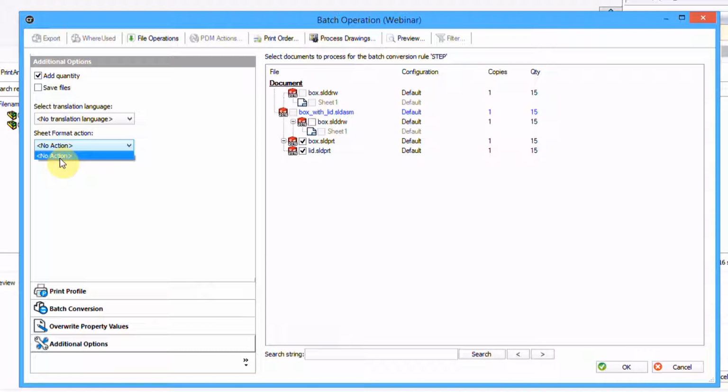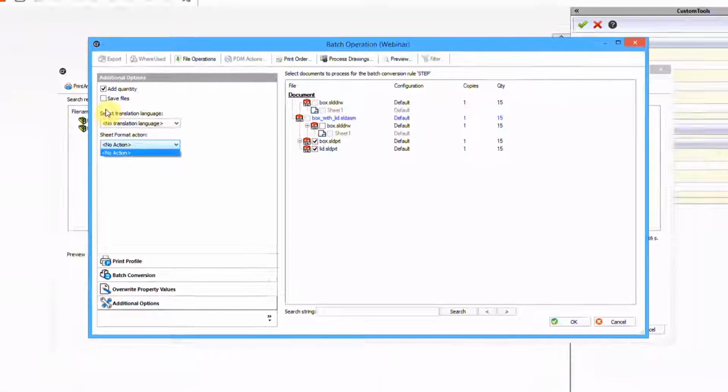So we've had some customers that used it to replace their own sheet formats with a customer requested sheet format, and then print a PDF, but left the save turned off. So that preserves it as their original format, but it creates a PDF of it with the swapped out format. So you can do that too, kind of as a batch operation. So it saves the user needing to do it on a sheet by sheet basis.